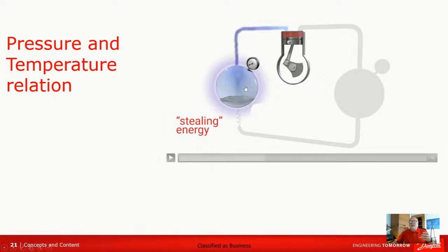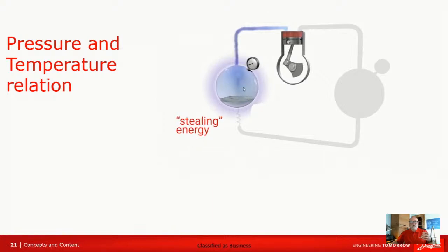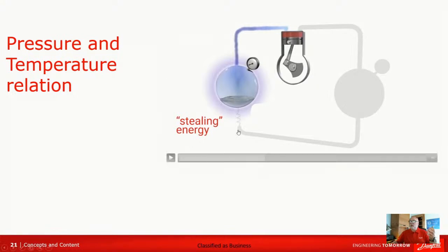It steals, you could say, or at least that's what I call it, energy from what is inside the fridge, like the milk or whatever, cheese maybe, and then it transports the heat, so to speak, into the vapor, the boiling of the isobutane.